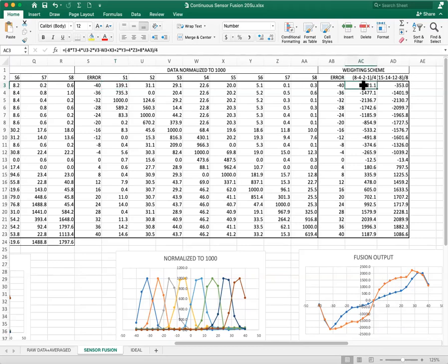But you can see what the calculation is. Here's the calculation. T3 gets multiplied by -8, U3 gets multiplied by -4, and V3 gets multiplied by -2, and we just add them all up. We're just adding them up and dividing by 4. That's how we get from 8 numbers down to a single number, and that's the whole idea of sensor fusion. Now, this is the simplest kind of sensor fusion that you can come up with.